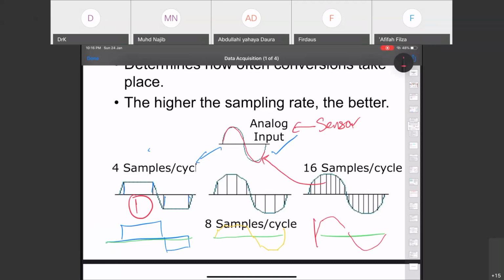If you look at the second one, you sample at a higher frequency but still not sufficient. You get something like a sinusoid, but it is not a sinusoid. Also information loss, and you are not working on the real signal from the sensor, because something is wrong with your sampling rate or sampling period.